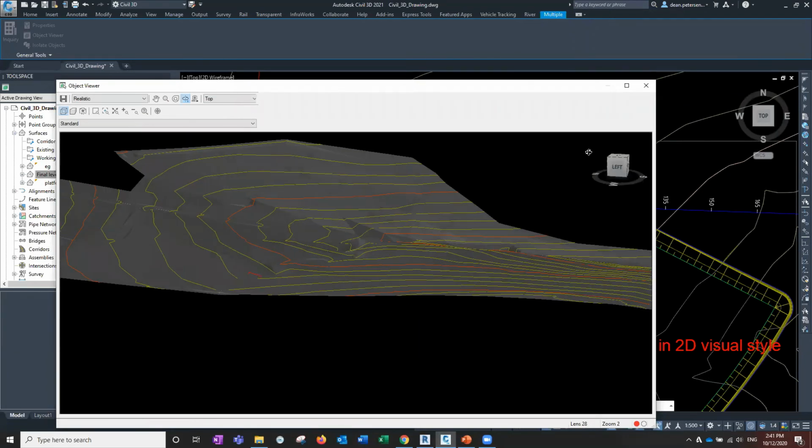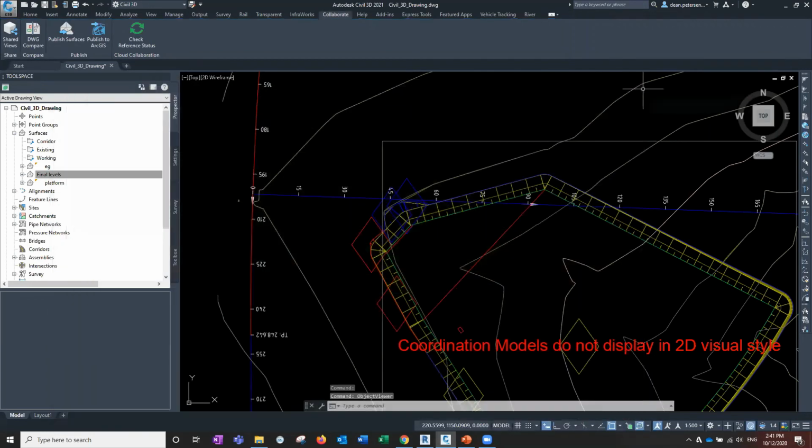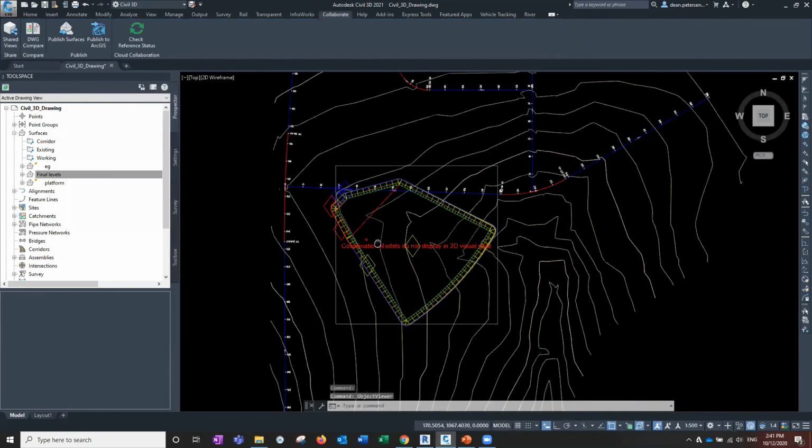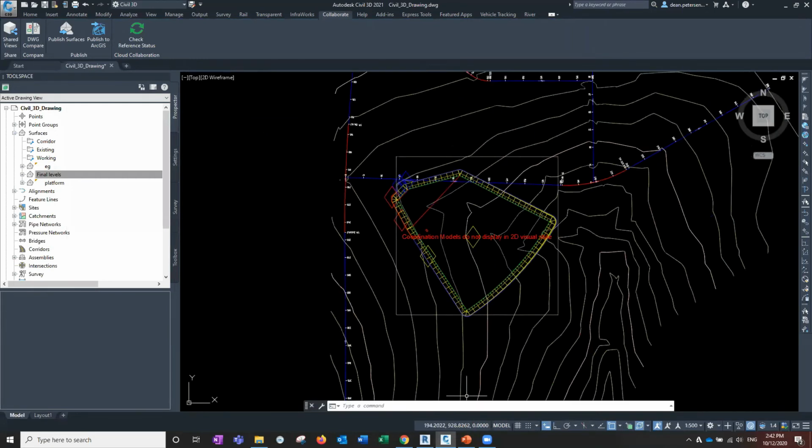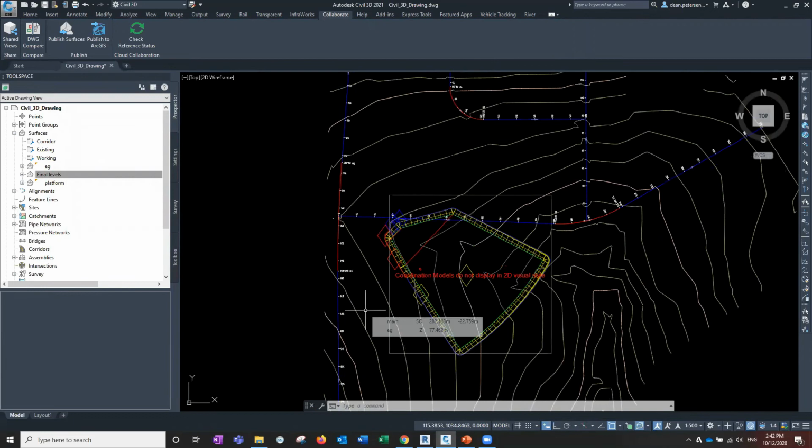If you're just looking for floor levels and things like that, we can simply go back into the 3D orbit where we were before and use your snaps. And when you snap on them, you're going to see the coordinates of the cursor down in the command line there. If you just want levels to floor levels and things like that, straight out the Revit model.